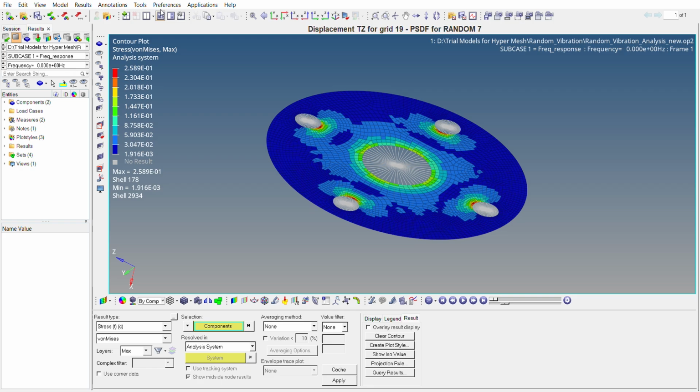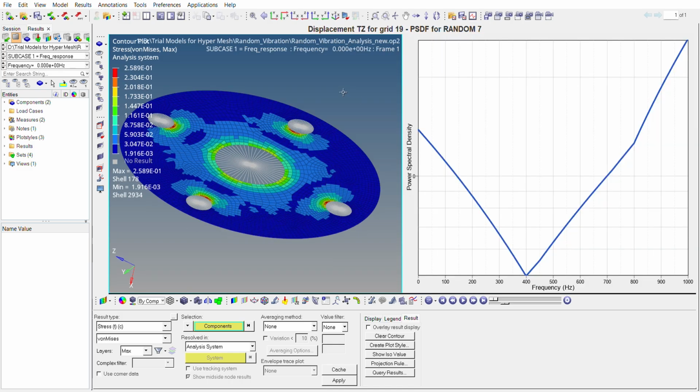So this will happen after you click on Optistruct and run the solver. Once it is completed, you can click on the results and a Hyperview window like this will open. Then you have to go to the contour tab and click on apply. This will come.